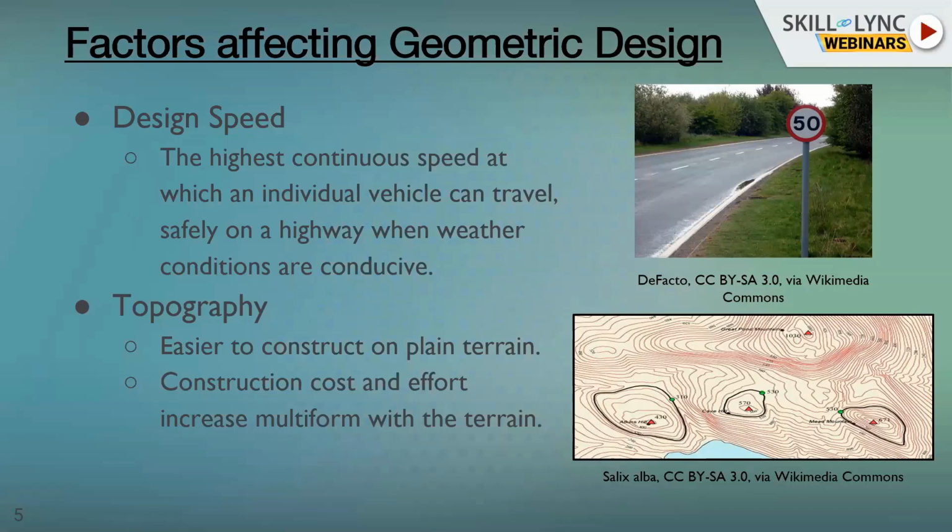So different speeds will have different radii and different super elevations. These are all interrelated, and you have to be very specific while picking them. So obviously even this design speed can impact your travel time, and even the safety in some conditions.